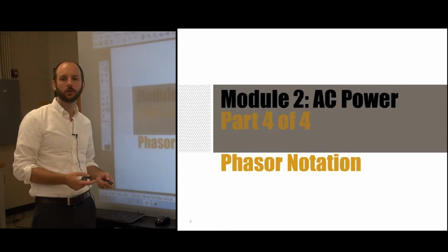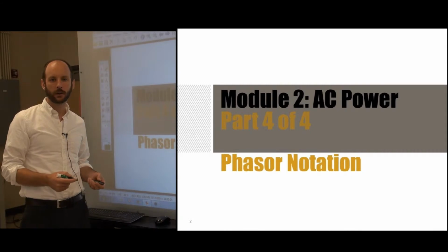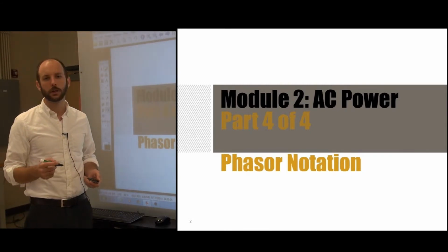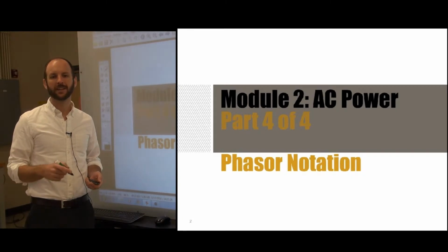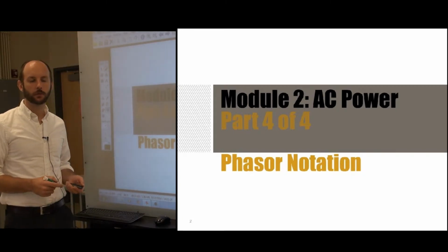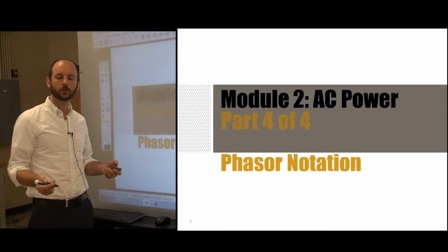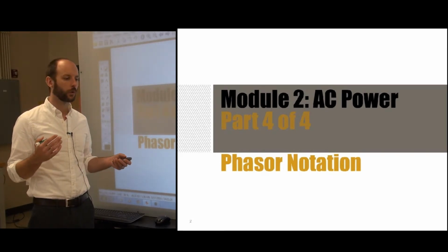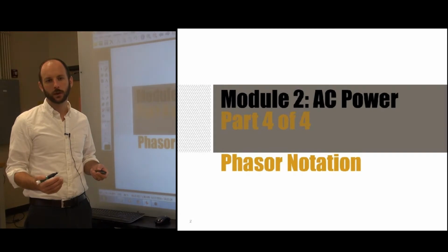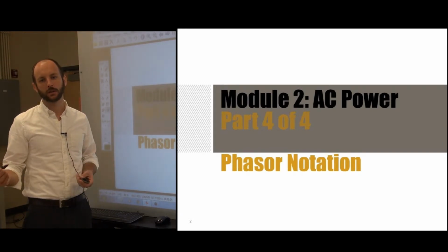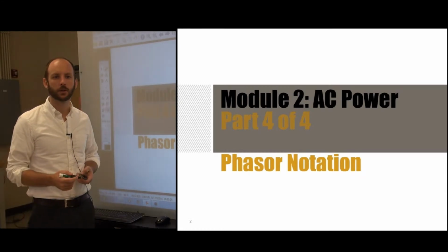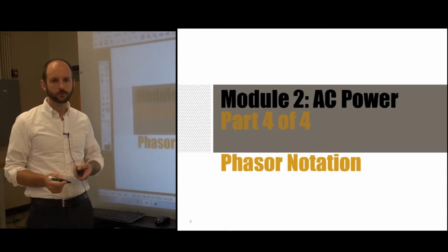Mathematically, we showed that we can use the RMS value to relate directly to the power that would be delivered by an AC source that's equivalent to the power that would be delivered by a DC source. So the use of RMS allows us to look at average power delivered over one period of a sinusoidal wave function and compare that directly to a DC source. They're equivalent: the VRMS and VDC end up being equivalent values.